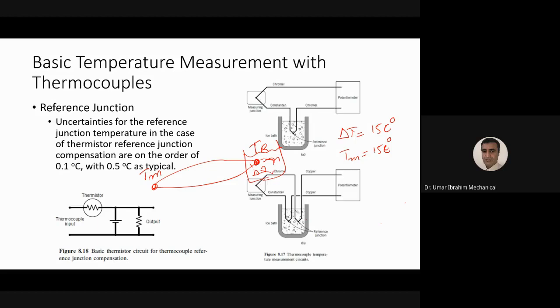The question then is, if we have to use another device, why do we use a thermocouple? Why not use the other device to directly measure the temperature? The answer is that a thermocouple has qualities compared to RTDs and thermistors that you will not find in either, and you will be forced to use a thermocouple even if you have to use a thermistor, typically, to find the reference junction temperature value. Clear, students?